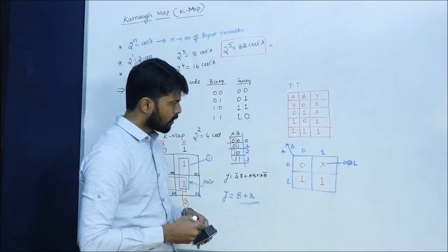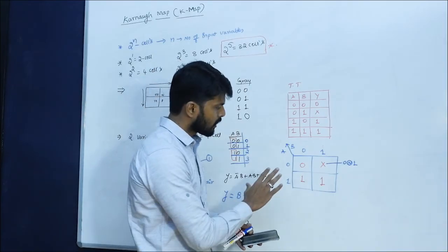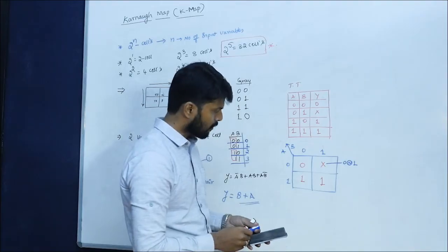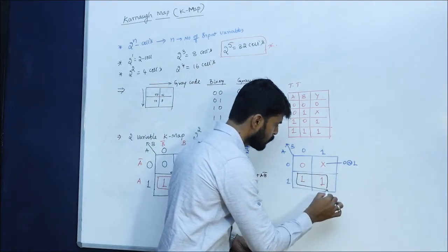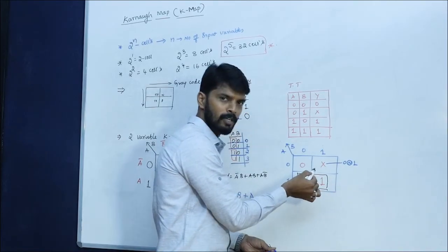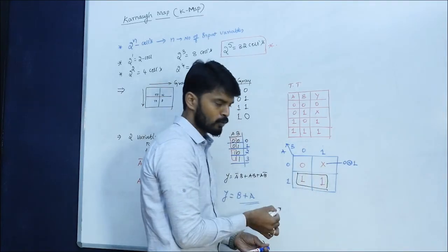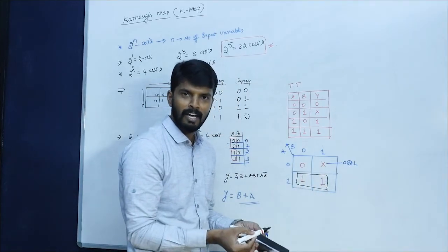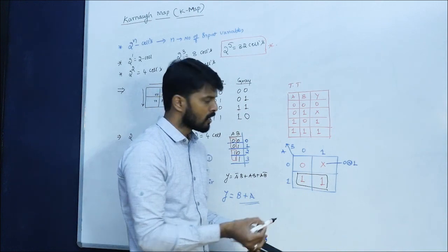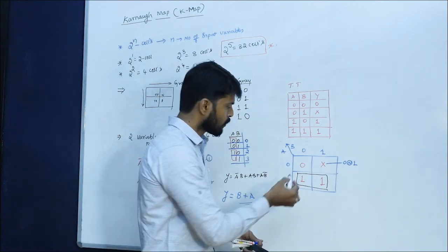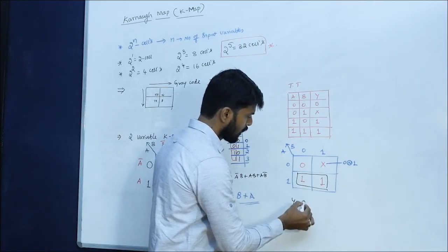Fine. Now, in this situation, I won't need to group with the don't care, because I am grouping the 1, 1 here. So no need to group with the don't care. In this case I am considering it as 0, because in my final equation I need as few terms as possible. So in that case I will take Y equals only A.